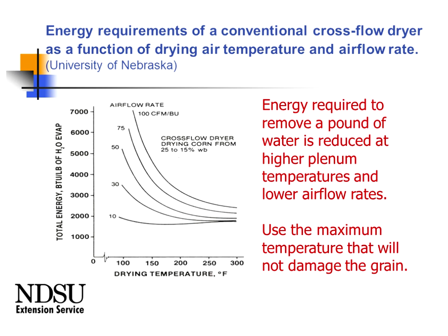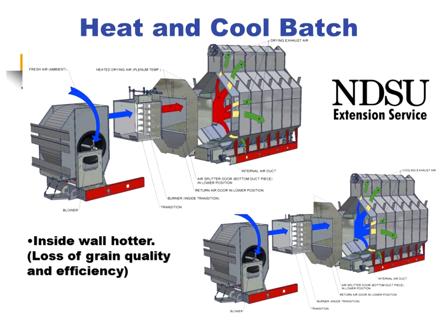And then, of course, the in-bin dryers, which this research wasn't done on that style of drying, but at this lower airflow rate, I think we can get the indication, again, that there's an optimum point for energy efficiency on the in-bin dryers, and that's roughly associated with that recommended 150, 160 degree temperature that we're using in those dryers.